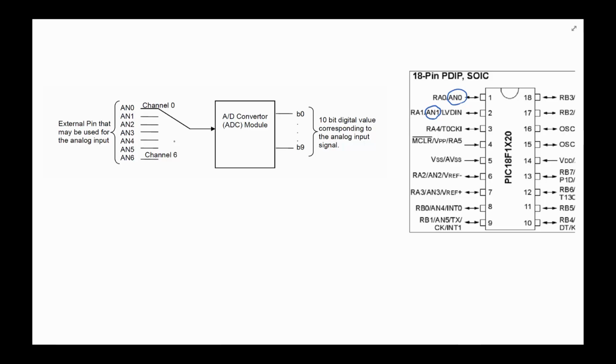And this allows you to take this thing and have, let's say, 10 different devices, in this case, 7 different devices, 0 through 6, and have one device come into channel 0, another one 2, 3, 4, 5, 6, and then you can move your A to D converter to read a different one and give you a value. And since you have control over both sides, you know what you're reading. So that's a way of taking one A to D converter and being able to read 7 different things.